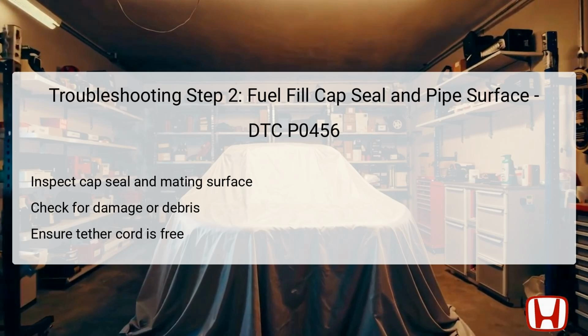Damaged seals or surfaces can cause tiny leaks that activate the DTC. If any damage or obstruction is found, replacing either the fuel fill cap or the pipe may be required. Verifying the integrity of these components helps eliminate fundamental causes before moving to more complex checks.